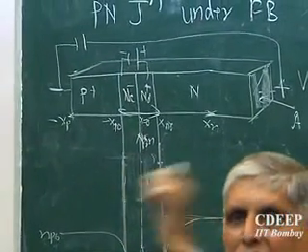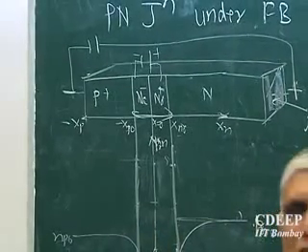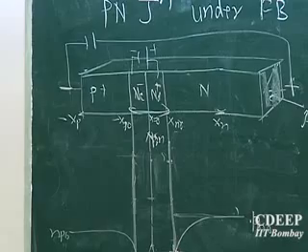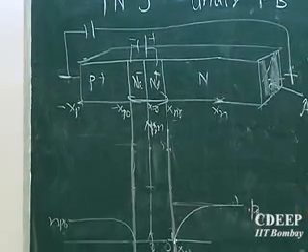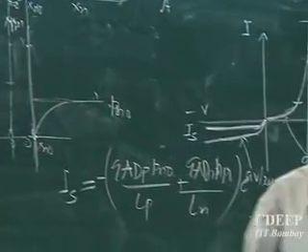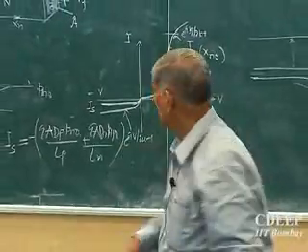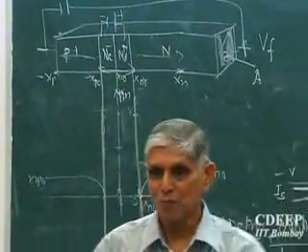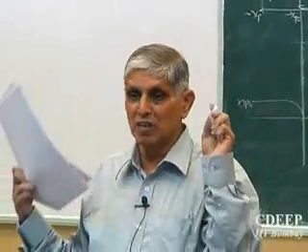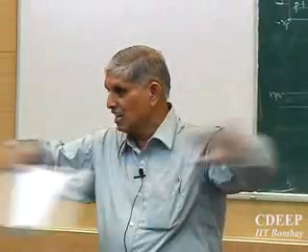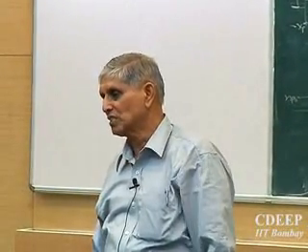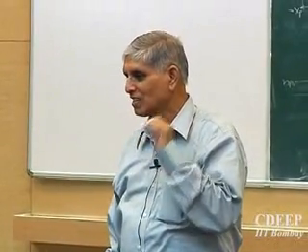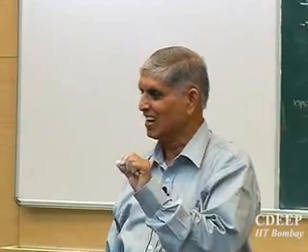Whatever is injected is received, and therefore, now this part is very interesting. What we are trying to say now is that okay, you have got this current fine, but why are the carriers still moving in the reverse bias? There must be an electric field which must be drawing them. Please remember, you have electrons here and holes here, they must be taken away at the ends. So in reverse bias, there will be an electric field which will pull these carriers to the ends and will constitute the reverse saturation current. Is that correct? So this fact that electric fields are zero should always be taken with a pinch of salt, because otherwise the carriers cannot be brought to the contact.